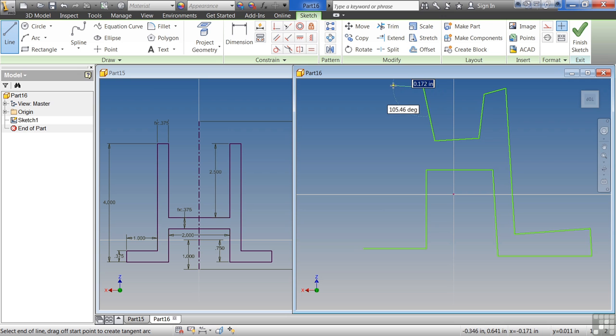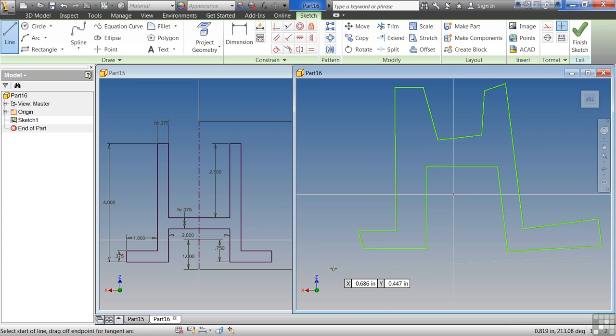You can see I'm getting the very, very basic shape down, but it's not exact. Those of you who are used to using direct input with AutoCAD, this is very hard to get used to. One of the things that I do is I actually adjust the shape and size of my design so that I know I need to manually come back and edit it. I assume if I see a perfectly perpendicular or parallel line, that Inventor's already added the constraints I need. So I will actually create something that looks a little bit Frankensteinish so that I know, as a mental note to myself, that I need to come back and finish editing the sketch.